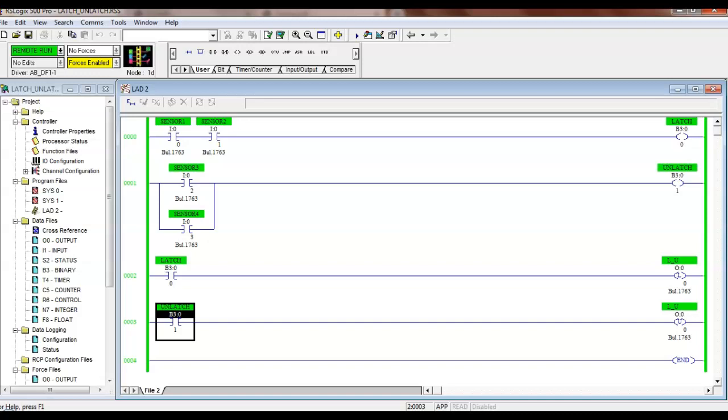But we're doing this with one coil. And like I said, we had these things on our radio controlled cranes, because every once in a while the operator would lose a signal because it's radio, right? Understand that? It's just like if you get too far out of range. Well, that sucker's got a big old electromagnet down there with a bunch of steel on it, and if it loses the signal, the magnet turns off and it drops all the stuff and kills a bunch of people. Well, they used a latching relay on that. So they would latch it, so even if they lost the signal, they kept power on the magnet until they did what? Until they unlatched.